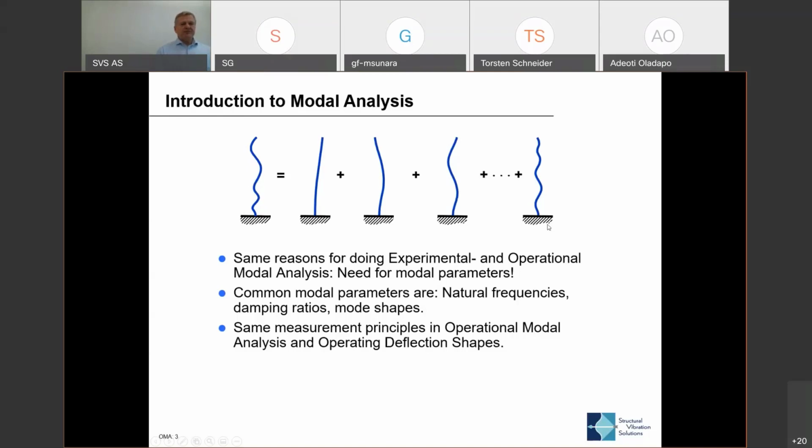The good thing is, when we are doing this kind of analysis here, operational modal analysis, we can actually do another kind of analysis also, because when we are doing operational modal analysis, we are working here in this domain here. This is the modal domain over here on this side of the equation. But you can also actually study the overall vibration pattern of the structure.